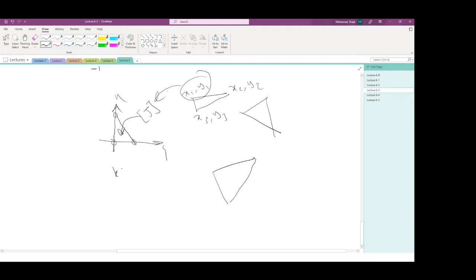So you do the stiffness matrix for this new element. So you have the expression for the stiffness matrix. You just need to insert the coordinate into the Jacobian. You get the stiffness matrix on the other side. This is basically how it works. So you have the expressions all happening in this local coordinates.